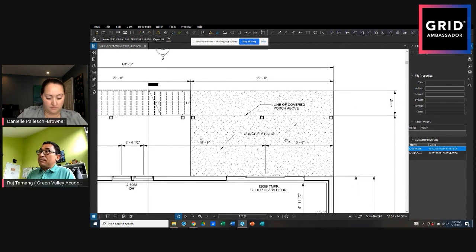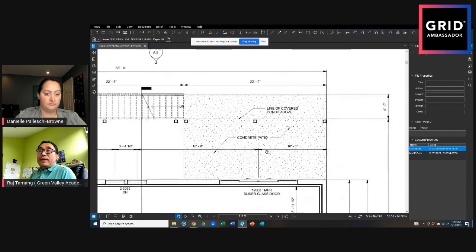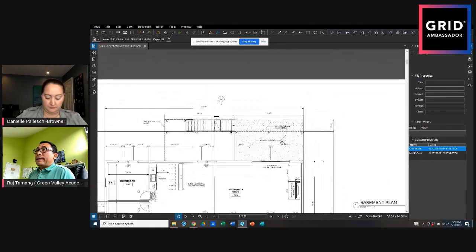Nowadays, there are some patios where, instead of doing concrete, you can have some permeable ones, so it doesn't look like concrete, but you can do some mix. So when it's raining, it doesn't really become runoff. It may infiltrate, right? Go into the ground. Those are okay, like cedar stones and things like that. Yeah, I've seen a driveway sometimes, or a parking lot in the front or back of the house. Those things you have to do, but again, you clearly mark this on the plan.